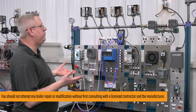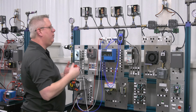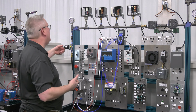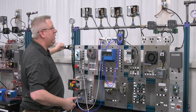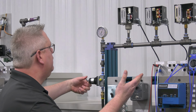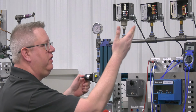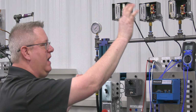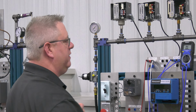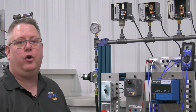So I'm going to run this pressure up, and like on this one, I've got the meter hooked up to the normally open contact, so when this trips, it should give us an audible alarm. Or will it? As I adjust the pressure upward going to that switch, it's tripped, and I can hear the mechanical switch making, but my meter is not indicating that my normally open contact is made, and that's on purpose.